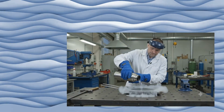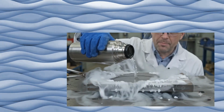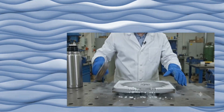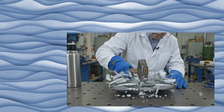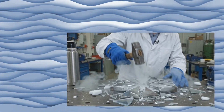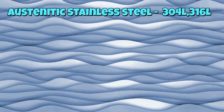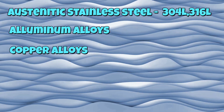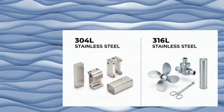This is where material science becomes critical. Structural carbon steel performs perfectly well at room temperature. At minus 196 degrees Celsius, however, it can lose its ductility and behave almost like glass. For this reason, cryogenic equipment is typically manufactured from materials such as austenitic stainless steel 304L and 316L, aluminum alloys, and copper alloys. The material isn't chosen for corrosion resistance alone. It's chosen because it remains tough at cryogenic temperatures.